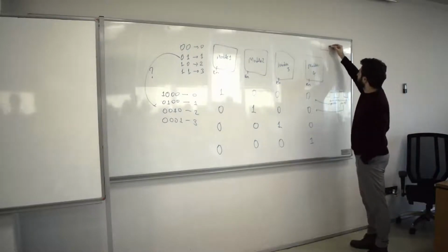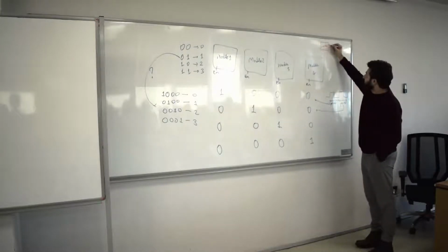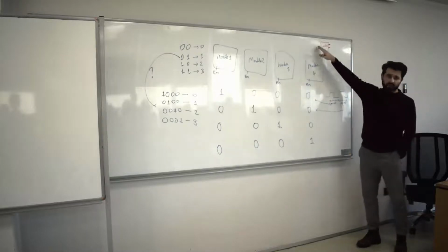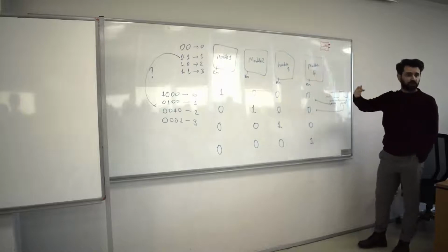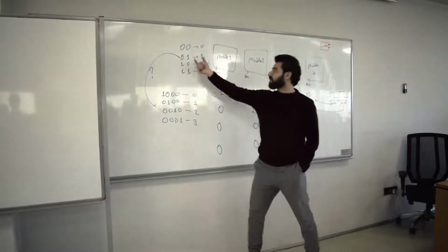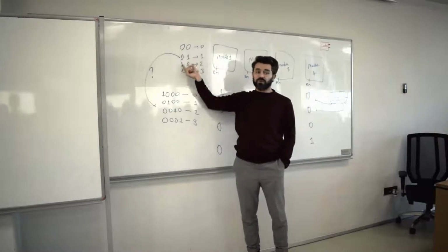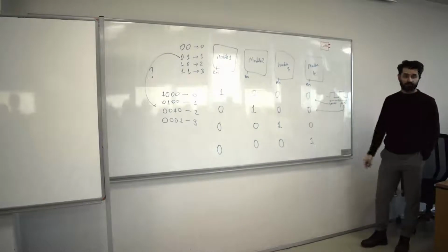So maybe if you have a conventional counter here that generates 2 bits. Remember that a conventional counter that counts forward does not need any input. It just counts, and it generates those 2 bits: 0, 0, 0, 1, 1, 0, 1, 1, and then goes back to 0, 0, 0, 1, 1, 0, and 1, 1, at every clock tick, every clock cycle.